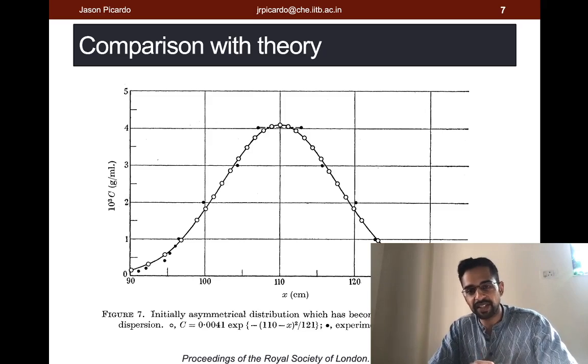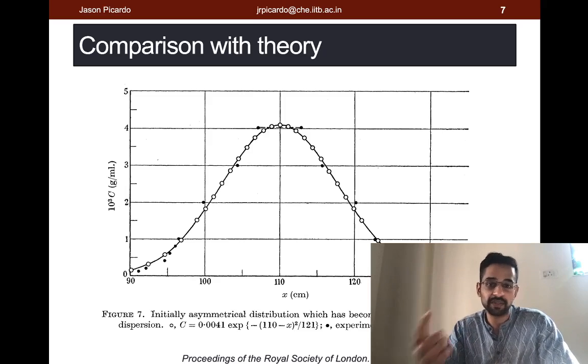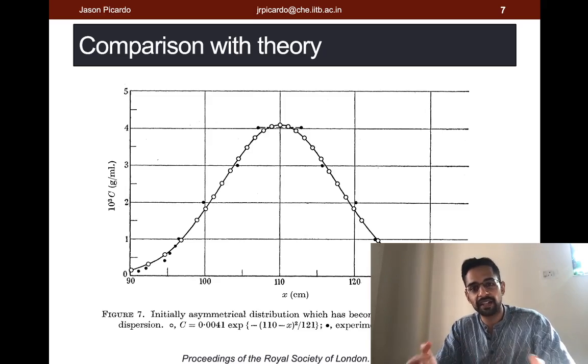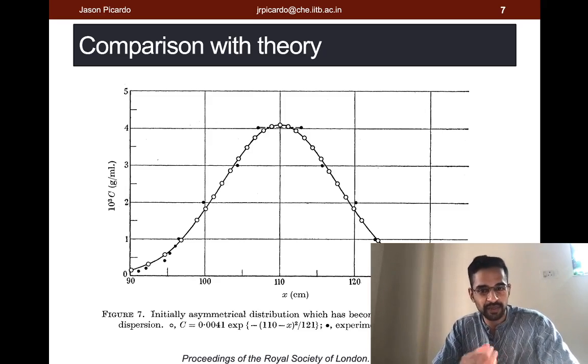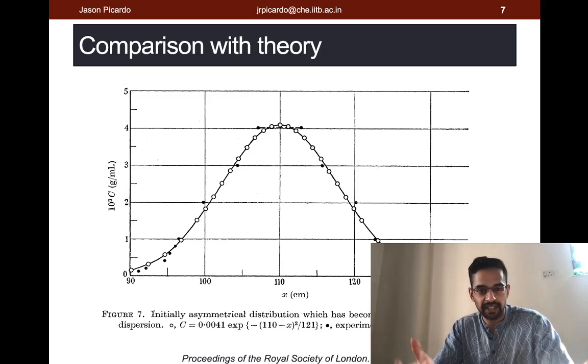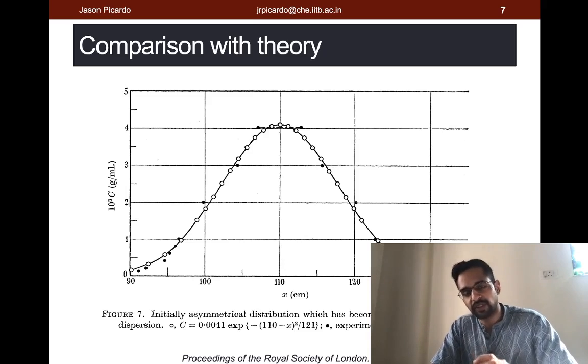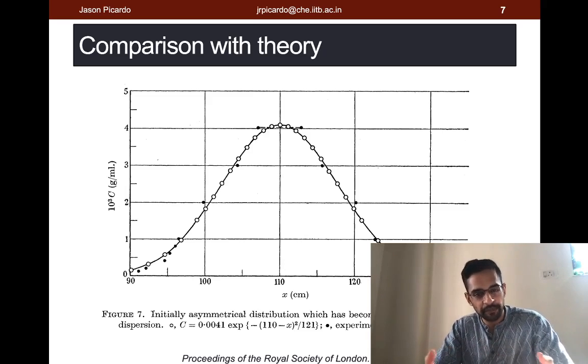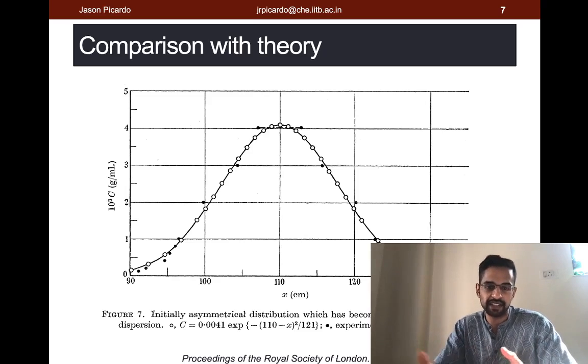And most importantly, we shall see that the dispersion effects depend not only on the velocity profile and on diffusivity, but also on the kinetics of the reaction, which is why RTD done in cold flow settings without a reaction is different from the RTD done in a reactor with a reaction. And so we will see how the method of averaging can be quite powerful for the more general problem of transport with reaction in the next lecture.